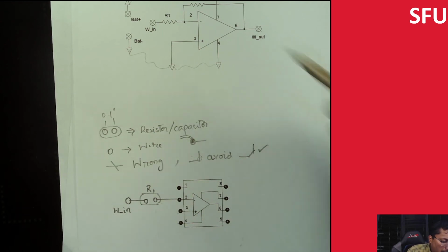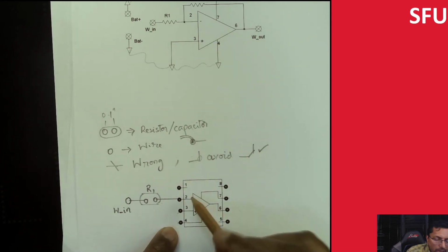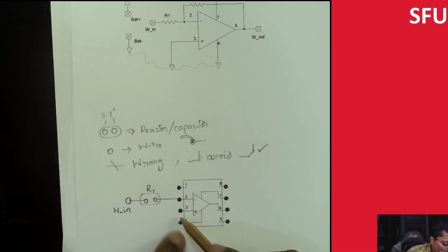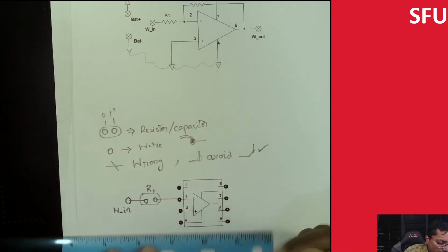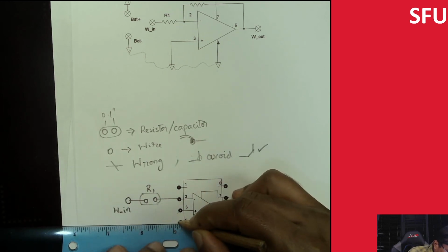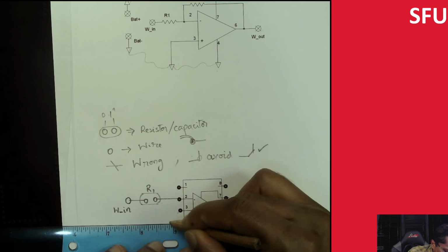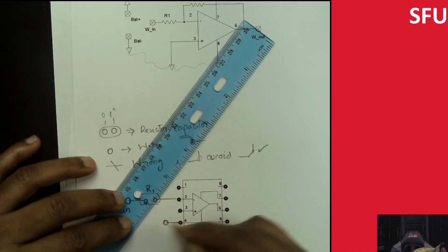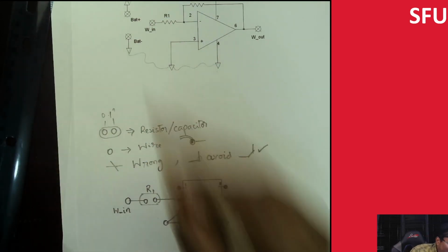So we come back to this. Let's go to the next pin. 3 is connected to ground. 3 needs to be connected to ground, and 4 is also connected to ground. There's nothing else, and then there's the battery. So nothing else is connected. What I can actually do is connect these two directly. Since I don't want 90 degrees, I can just do 45 degrees like so. Wire here. And we'll just call this battery minus.